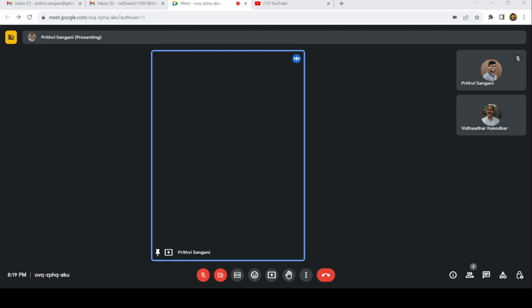So delta 1 can be found out by actually replacing it with unit load. What I'll do is replace it with unit load 1 kilonewton, and then because of this 1 kilonewton, let me say I have internal forces generated because of that, and I'll write it as ui's. Okay. Now how do I find delta 2?